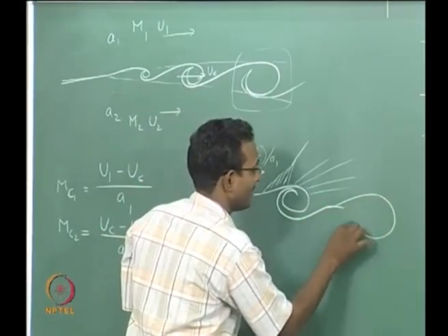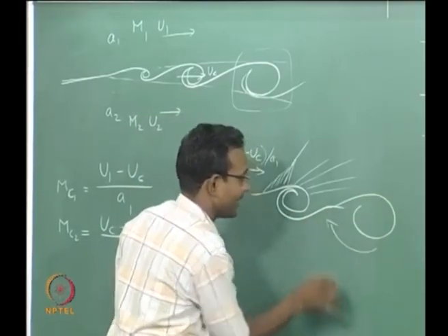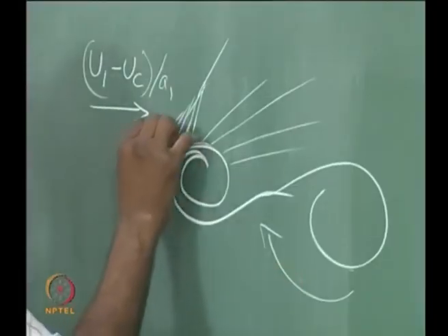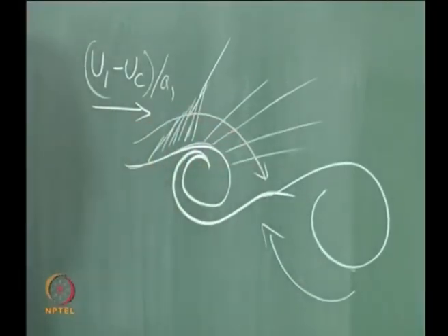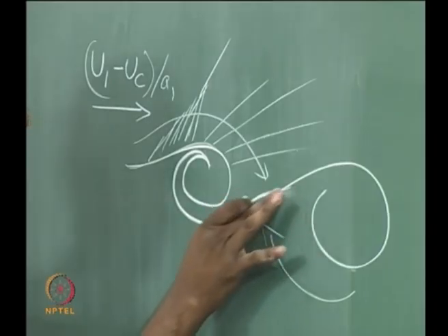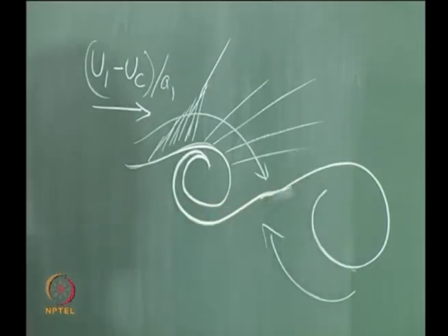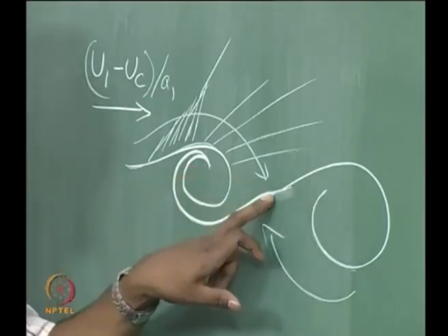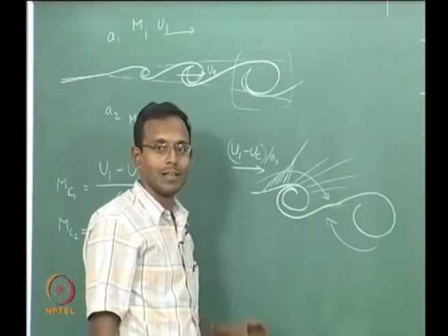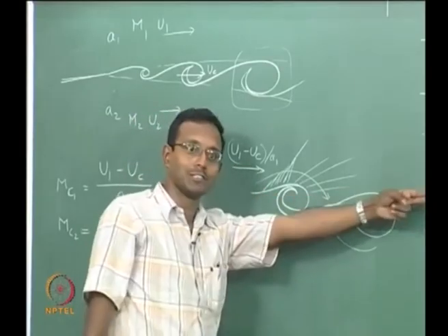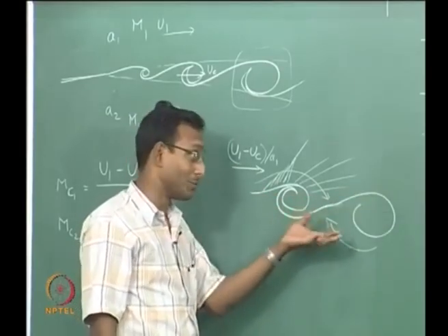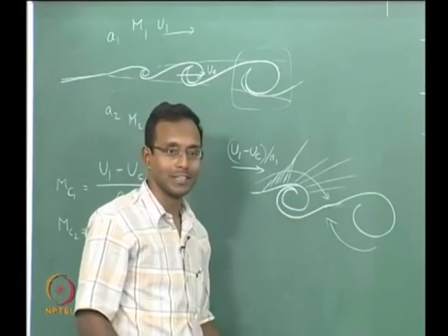The next guy is sending fluid this way in, while this guy is sending fluid out this way. They are going to find an intermediate locally, something like a stagnation point there. It is not really a stagnation point, with respect to these two structures it is like a stagnation point. Okay. Overall it is also having a convective velocity UC, which we have neglected, we have removed, so we can see this particular thing happening.